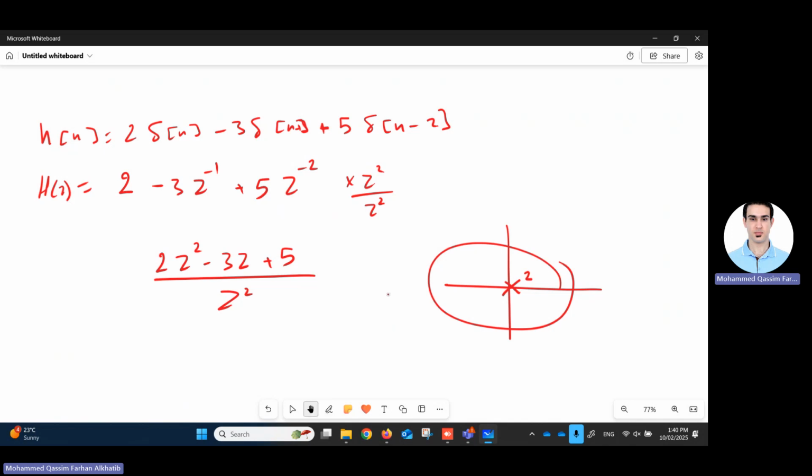Whatever the filter is, you will always have a z to the power n here. So that's why it is always stable. Your poles are always at the 0. And you can play with the variations of the zeros of the transfer function. From there you can play around with the phase transition and stuff, but with this filter you are guaranteed that it is a stable filter.